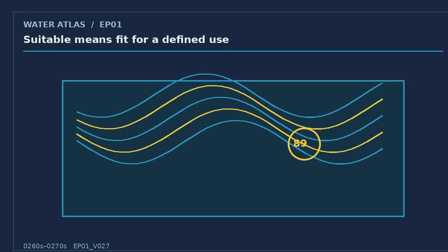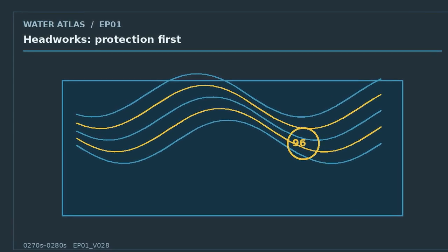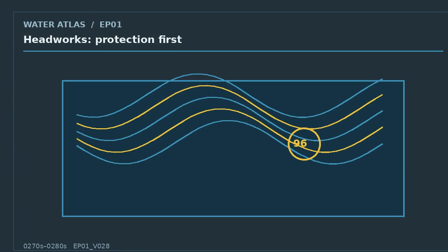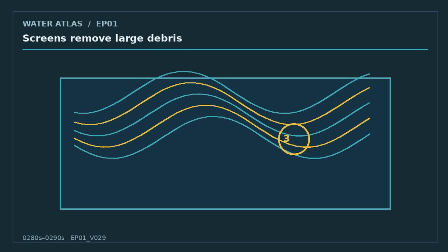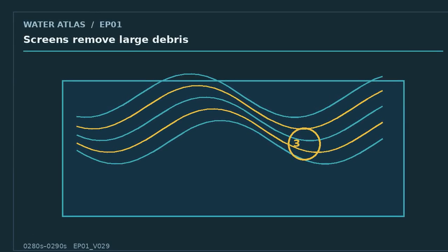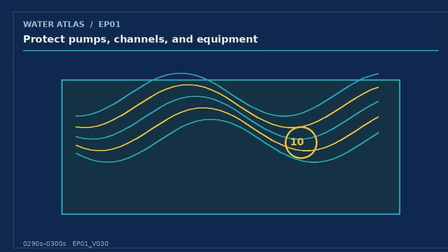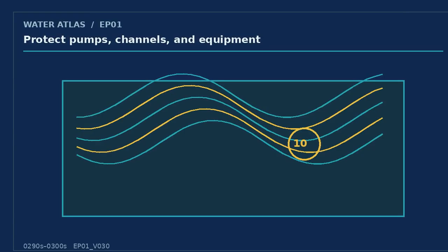Mechanism. The biological stage is where the invisible labor begins. In many treatment systems, microorganisms metabolize organic matter under controlled conditions. Engineers provide the hydraulic residence time, mixing, and aeration. After biological treatment, secondary clarification separates the treated water from the biological solids. Some solids are returned to keep the microbial process active. Excess solids are removed for residuals handling. This return and waste decision is a control point.